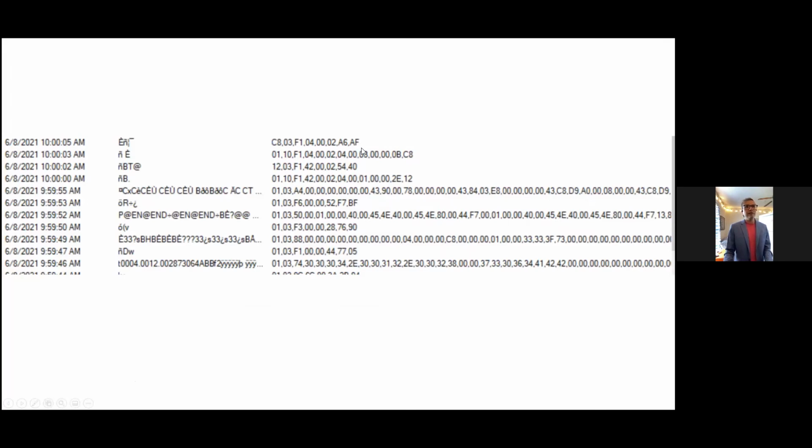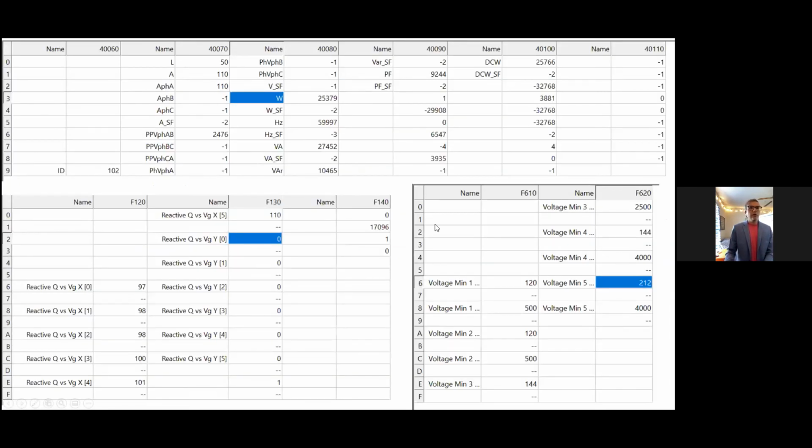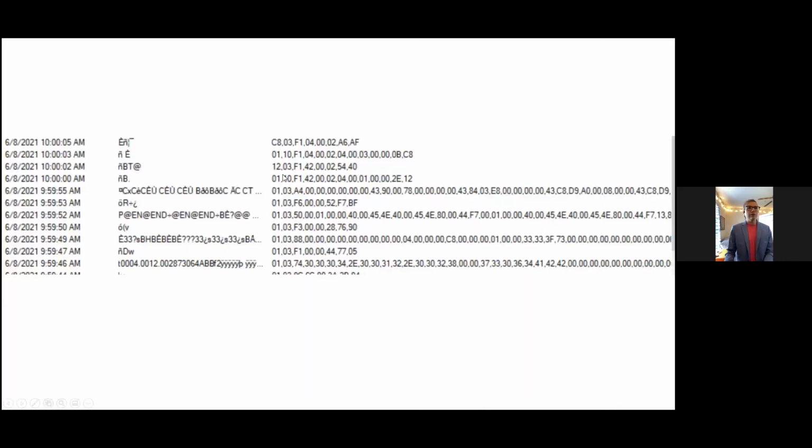So you have a request, which is this short message, and then you have a response, which is this longer message. Request, response, request, response. And that's the flow. That's how these machines talk to each other, is these numbers flow back and forth. And basically what it's saying is the request would say, hey, I am interested in reading these particular Modbus registers. Please tell me what the values in those registers are. And then the inverter responds that says this register is this value and this register is that value, on and on.